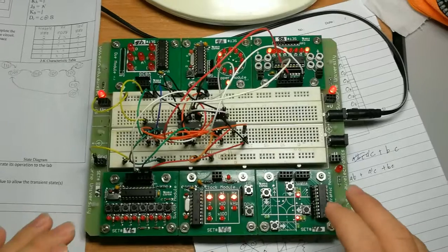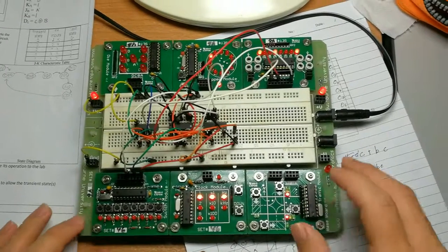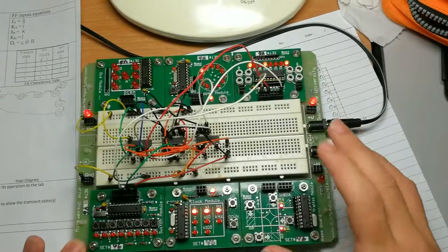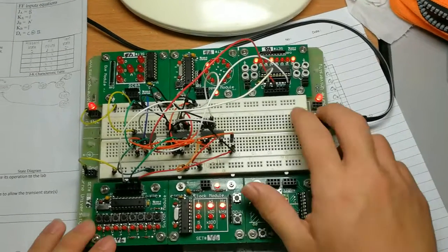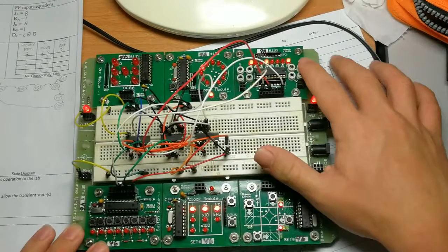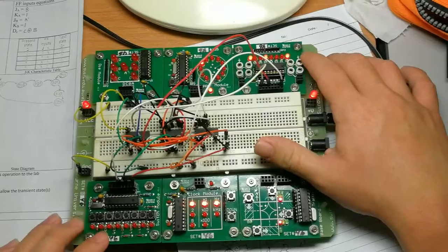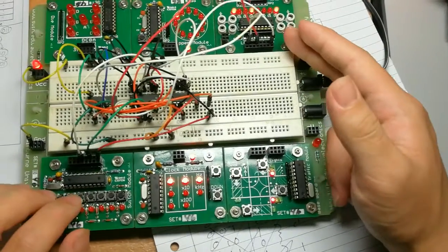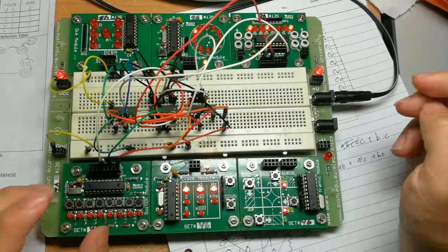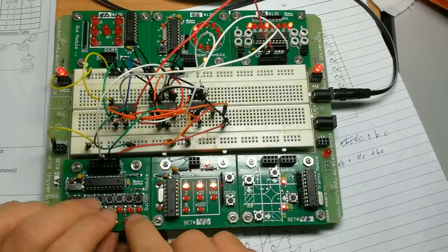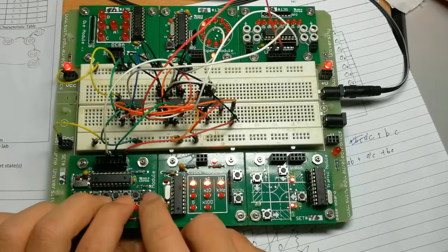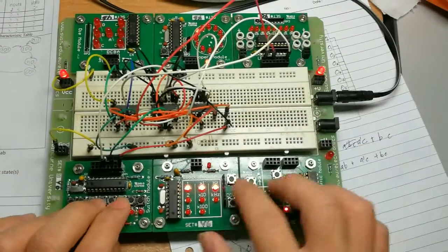Thank you. And now we are going to show the states CBA which are not in the loop, which are 1, 1, 1 and 0, 1, 1. Now CBA is 1, 1, 1, and the way we force 1, 1, 1 to follow the transition states is we force KA and KB to become 1, and we press, then it will become 0, 0, 0.